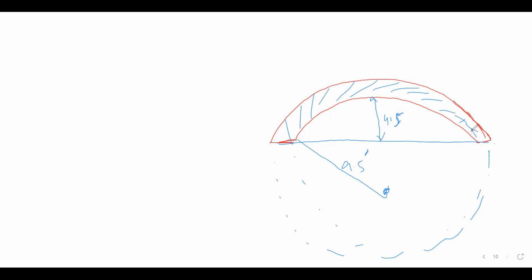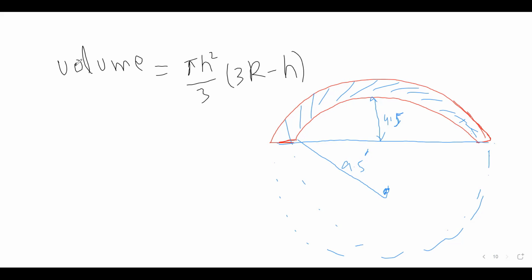All right, so we have this information, and we are asked to determine the volume of the same dome. Okay, this is not an arch, okay? It is a dome. Let's just calculate it. So the volume of the dome can be now, if you remember, for a solid, it was pi h square by 3, and then it was 3r minus h. But this time, as you can see, it is segmental as well as hollow. This formula is for segmental, but it was just solid.